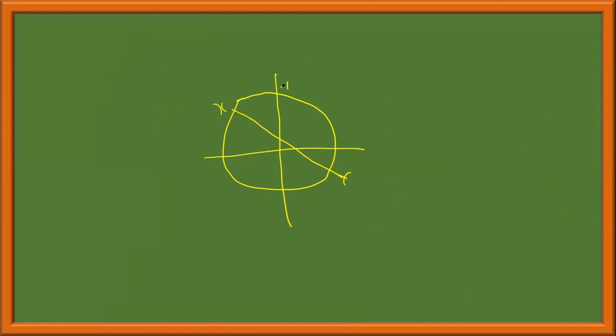This is my tau max, tau minimum. However you got it, to get that 120 degrees, I have to rotate in the clockwise direction by 120 degrees. I have to rotate this line by 120 degrees. Keep the protractor at the center point and rotate it by 120 degrees.